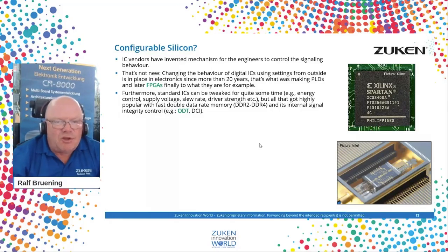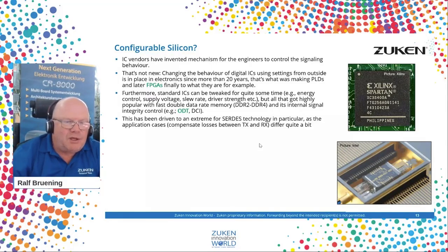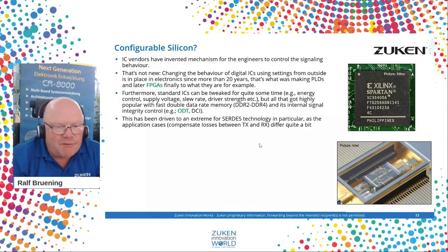Tweaking ICs is not new. But these days, we can tweak the electrical behavior in a more extended way. So DDR memory knows on-die termination. They know digitally controlled impedance. And for SerDes, we now have filtering technologies on driver and on receiver side. We have things called pre-emphasis and de-emphasis.